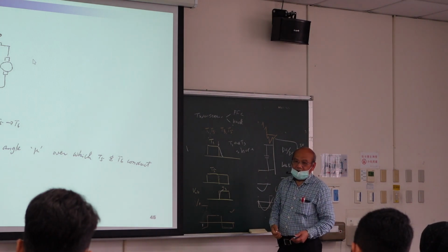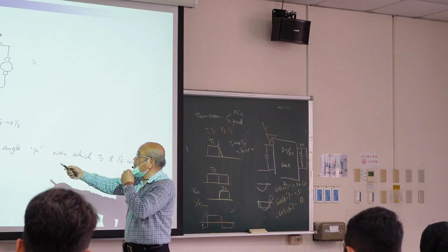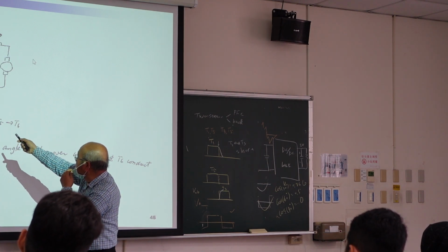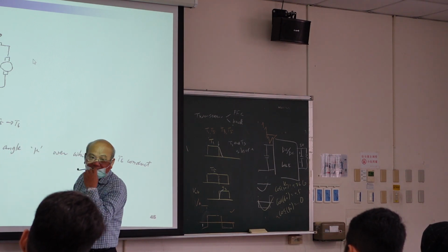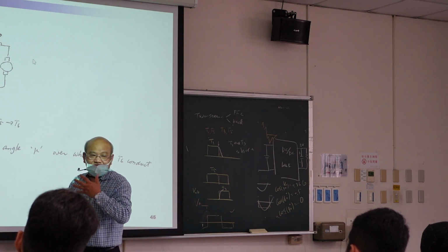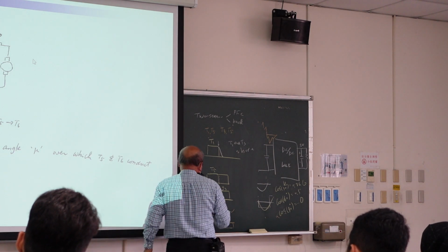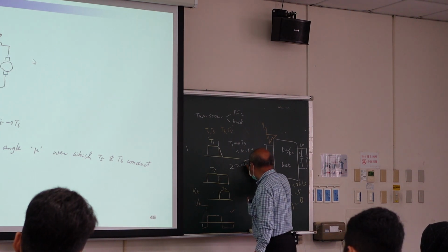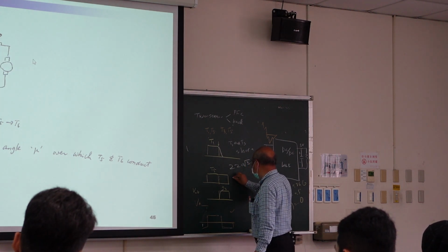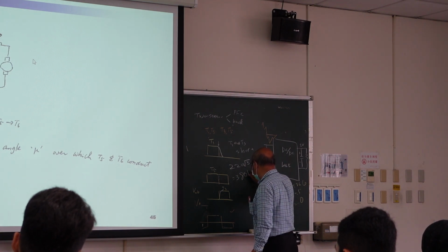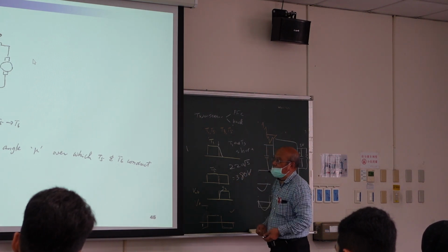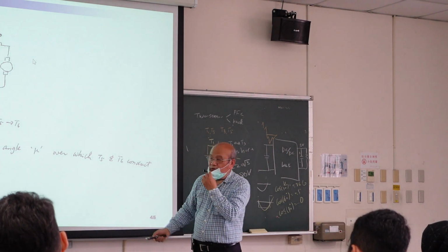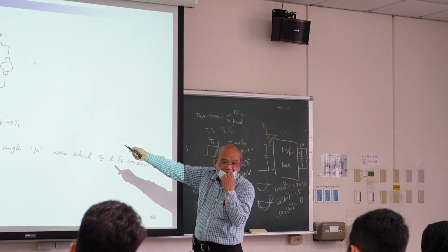Short circuit. So you can have T1 and T3 short circuit, which means A and C short circuit, right? What is the voltage between A and C? It is 220 volt multiplied by square root of 3, so maybe 380 volt short circuit. Then what happened? We create a huge current here, right?